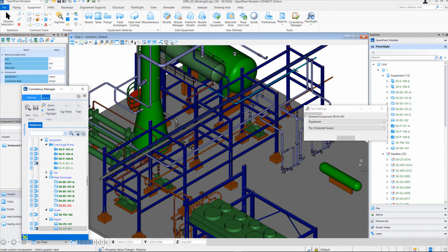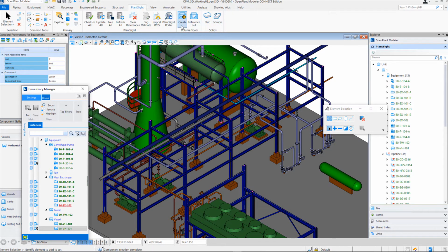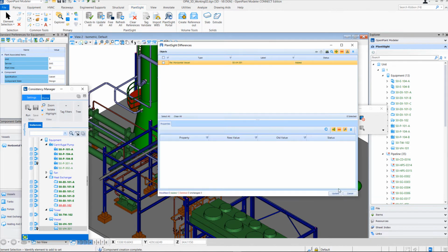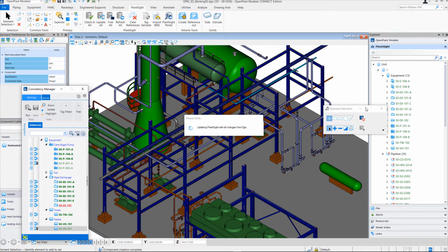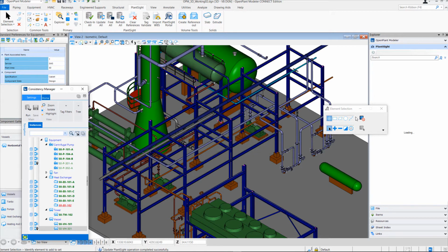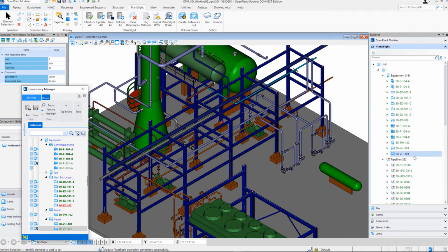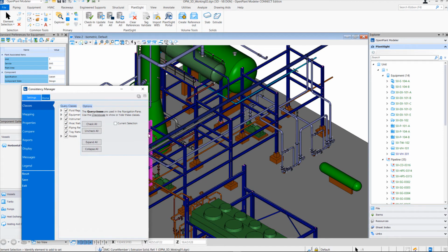Here we are selecting a vessel tag that has been placed in P&ID and then selecting to place custom equipment and picking up custom graphics in the model to complete the custom component creation. All information that is defined in P&ID is used to keep data consistent between 2D and 3D. This component can be easily checked into iModel using plant site check-in or update operations.